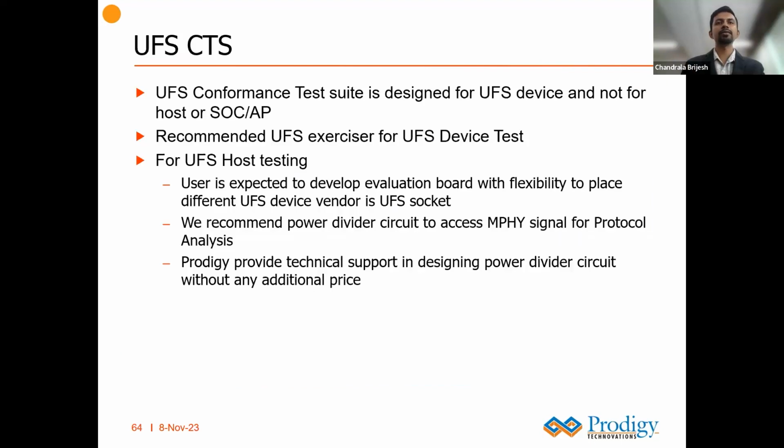Next. Yeah, so I'll give this CTS demo. Okay, the UniPro conformance test is from MIPI, and the UFS conformance test is from JEDEC. So we have implemented both the CTS, and some recommendations are there for the emulation. So whatever exerciser we have, it is a host emulator. That will generate host traffic, and you can test your device development board, or if the chip is available, you can test on the chip.